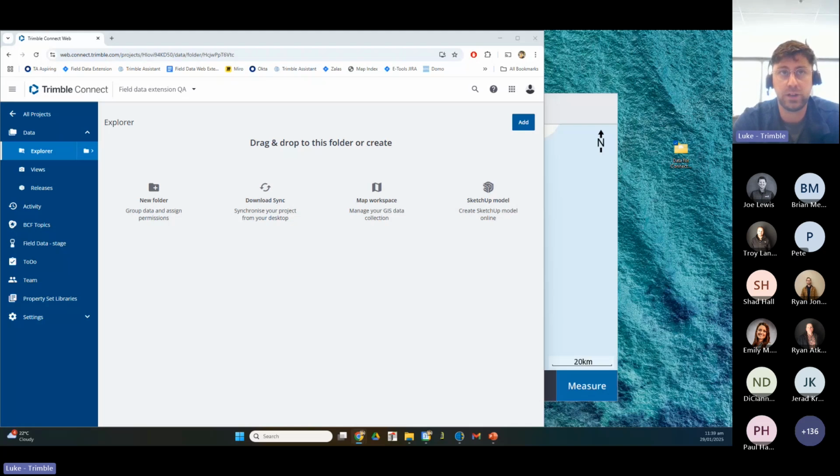So this happens when I think you've got a job that you've already done some things. Now, when you click merge data, it should merge the data. It sounds like we may have a TBC bug there where when we bring in a job that's maybe half complete and then you import that job again, and you want to keep the Office edits that you've done on the first half of the job. It sounds like there may be an issue with TBC there.